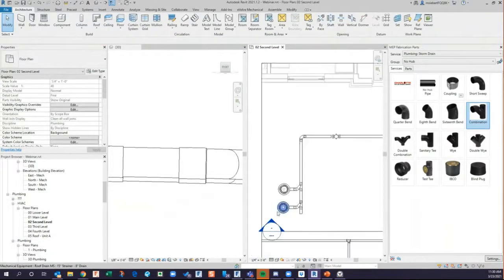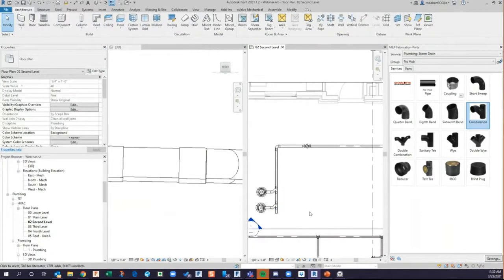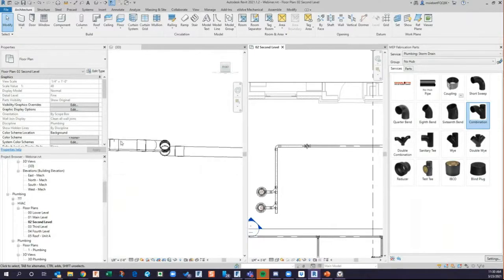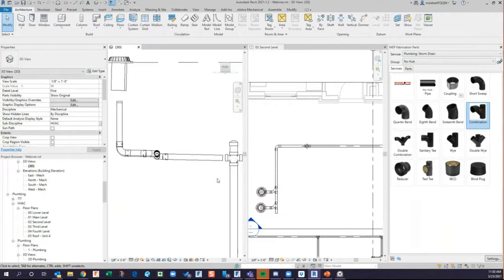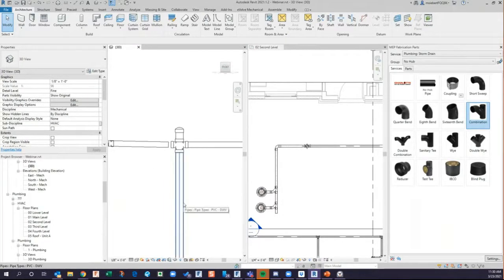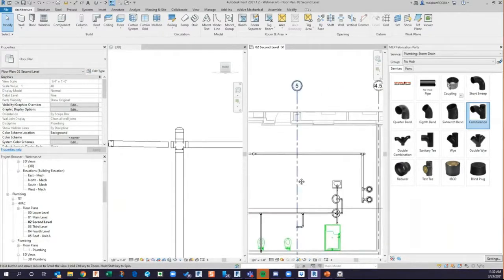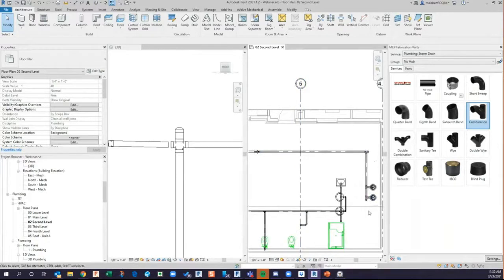So right here, as you saw, I've got this all ran out. Now I can actually run that connection back to my T once I convert this, okay? So as you see, that took me 10 minutes just to do this little storm drain, okay? What I want to do now is I'm going to do the exact same thing on this longer route, but what I want to do is I'm going to draw it freehand.